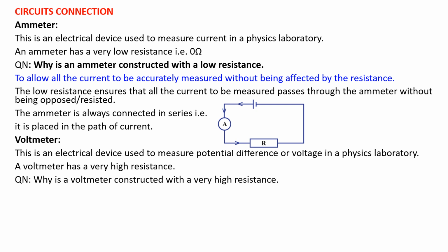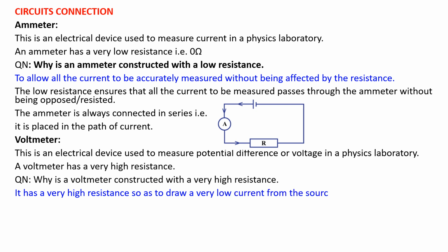It just measures the potential, the amount of energy required to push these charges from one end of that appliance to the other end. I mean, one end of the conductor to the other end. So its role is just to measure, not to consume current. It has a very high resistance, so as to draw a very low current or no current from the source, thus not affecting the total current in the circuit.